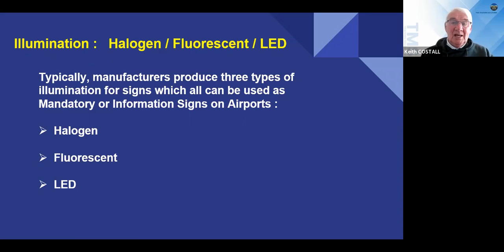And as a DC component, of course we have to have more electronics in there to be able to convert, if we're going to connect it to a CCR, which is an AC output. That's another subject, whether we use thyristor-based CCRs or IGBT transistor-based CCRs. That's also another factor that comes into the equation.